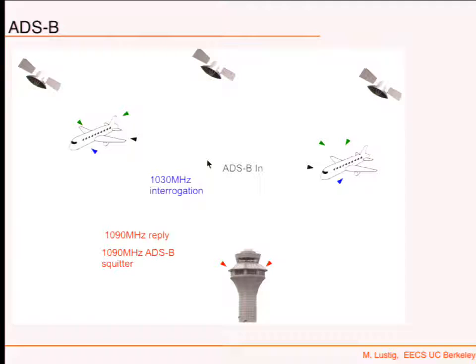Unfortunately, also fake it. So if you have a software-defined radio and you're malicious, then you could fake it and create fake airplanes. This is not even amateur frequencies. Everybody can buy a software radio and do this, which is a problem in terms of safety and security. But it's a secondary system, not the primary system. I think people maybe thought about it, but didn't think about it so carefully when they designed that system originally.